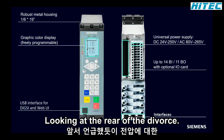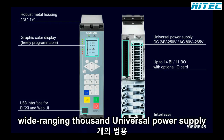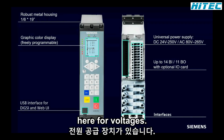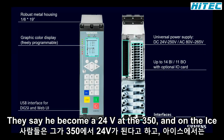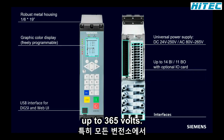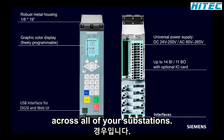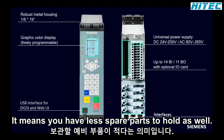Looking at the rear of the device, as I mentioned earlier, there's a wide-ranging power supply. There's only one universal power supply here for all voltages. DC, we cover 24 volts up to 250, and on the AC side, 80 volts up to 265 volts. This reduces the amount of variance required, and particularly if you're using various auxiliary voltage levels across all of your substations, it means you have less spare parts to hold as well.